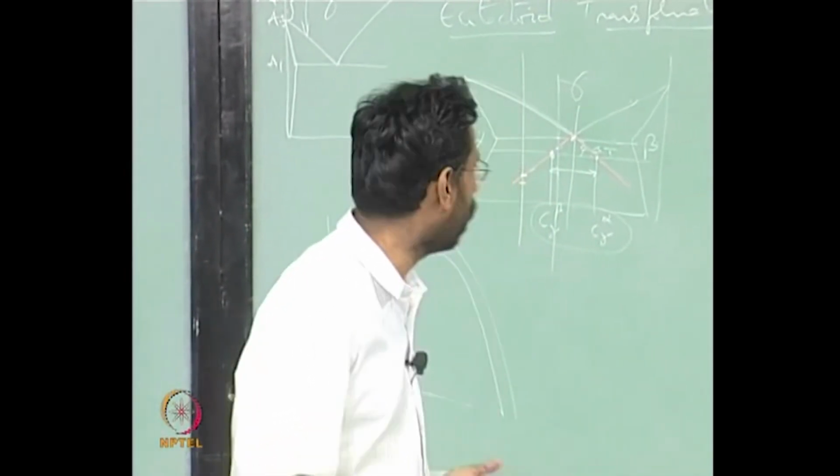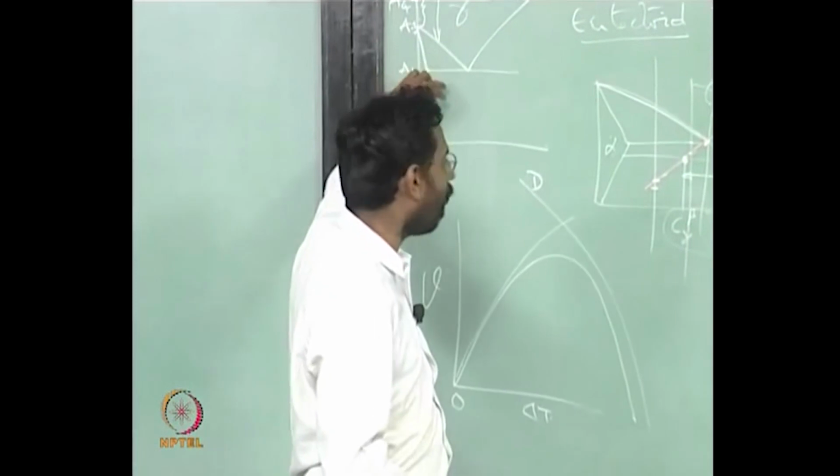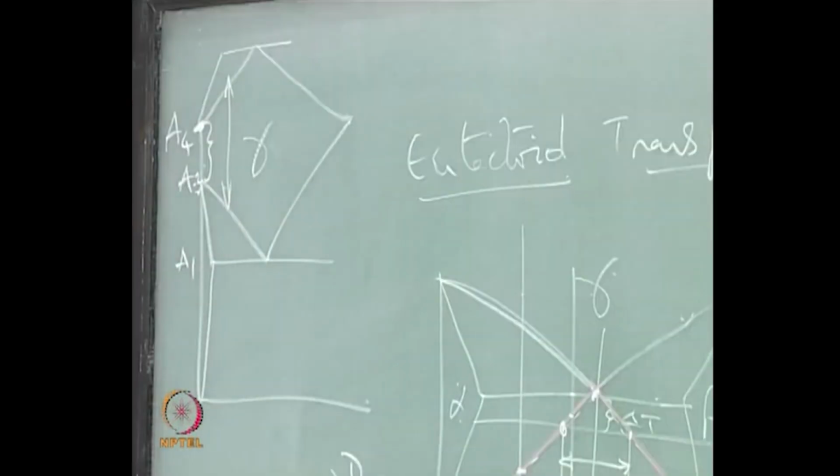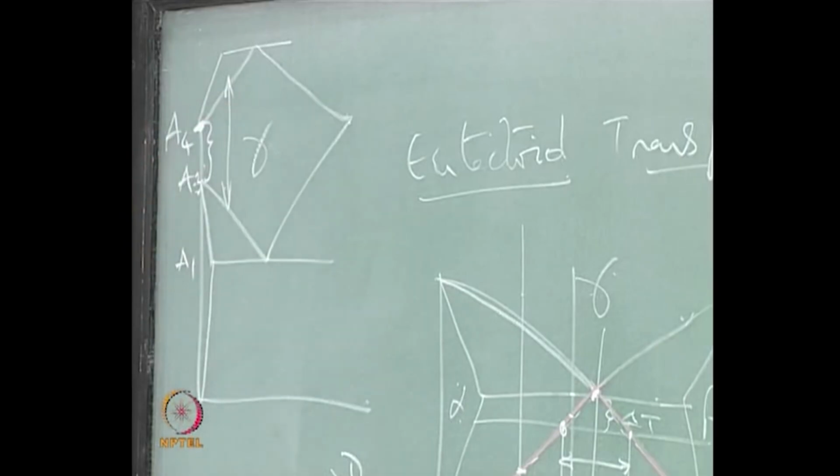This is because carbon wants to be in an FCC structure rather than in a BCC structure. So the alpha it tries to depress, gamma delta also it tries to depress. So the stability range of the delta gets reduced and the stability range of alpha gets reduced, so that you get gamma. That clearly tells you that carbon is a gamma stabilizer.